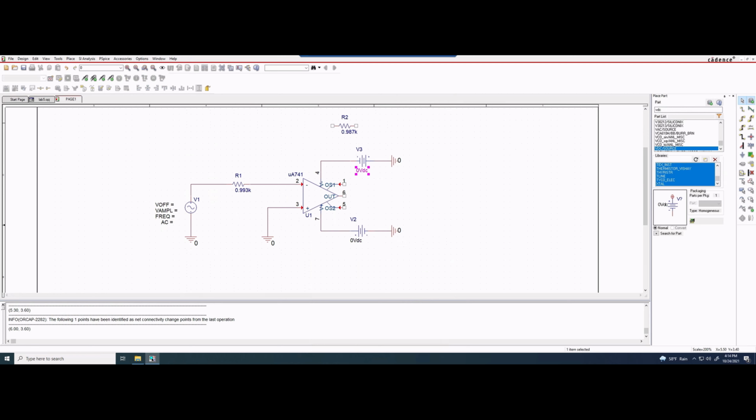So our voltages for these we measured as 3 volts and negative 3 volts. However, when we type it into this Cadence Release PSpice, we're just going to have 3 volts and 3 volts because we have this negative V right here that'll automatically take care of it for us. So we don't need to worry about making this negative.